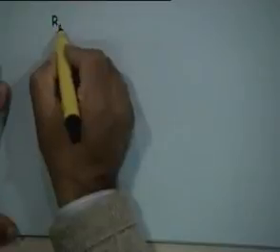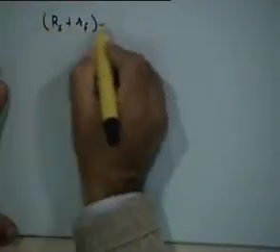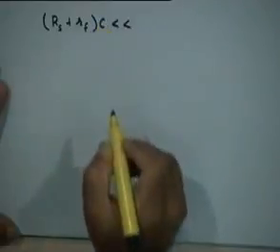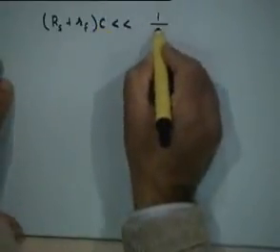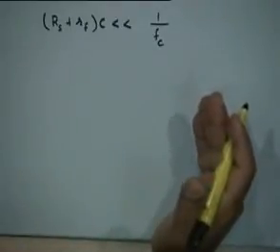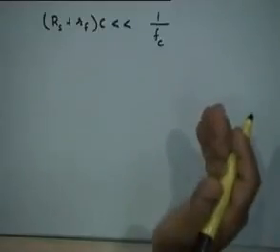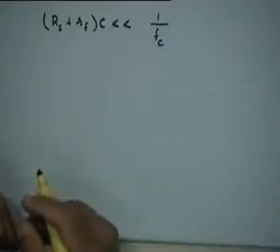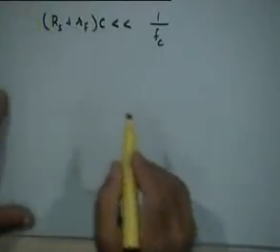So the point is that for the charging time constant, the condition that we should have is that this time constant is much less than the reciprocal of f sub c, which is the time period of the carrier wave, right? It should be much smaller than that, so that the capacitor immediately charges the moment the diode starts to conduct. It follows the half cycle of the carrier wave as it comes during the positive half cycle, right? So this is one condition that is required.